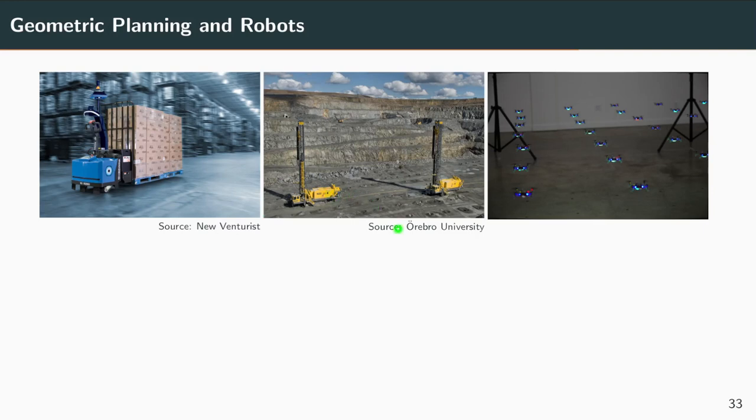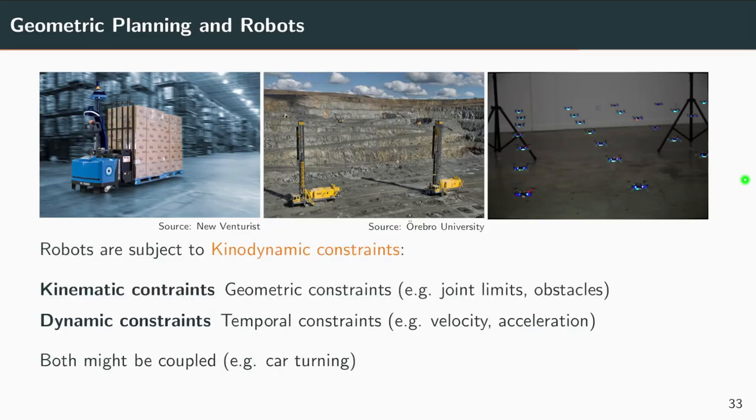If you have these sort of drilling robots, kind of a similar thing, they can't really turn in place, right? They have these very large turning radii that you need to consider. And then finally, for the flying robots, there's also this problem with the downwash I talked about at the beginning, and that the flight dynamics are pretty far away from just moving some body in 3D space.